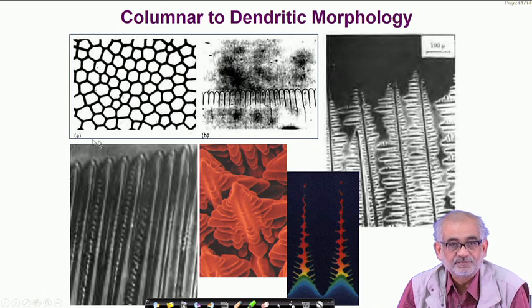So if heat moves out of the wall on this side, along this side wall, in the direction from right to left, then we expect the solid to grow from left to right, in exactly the opposite direction. So in this particular case, possibly the mold wall was somewhere at the bottom, and that's why the directionally grown solids actually grew to the top.